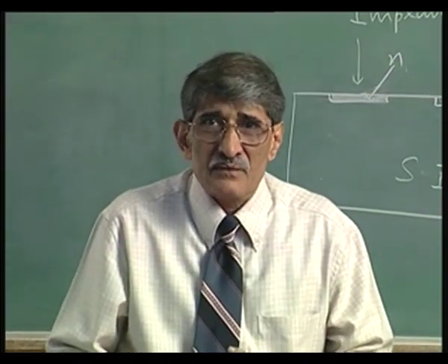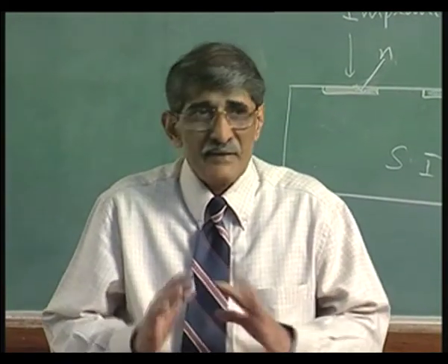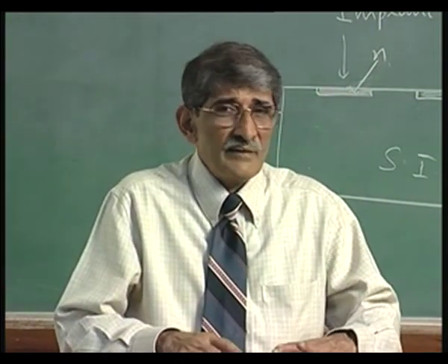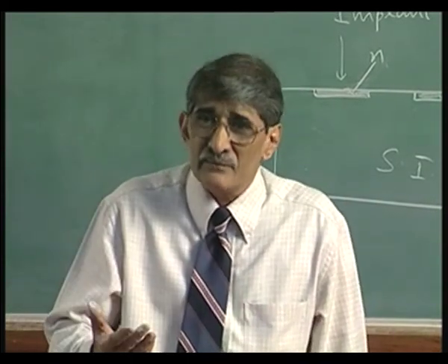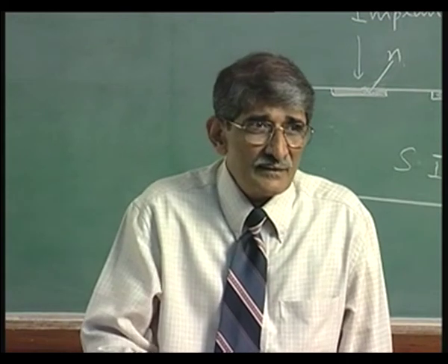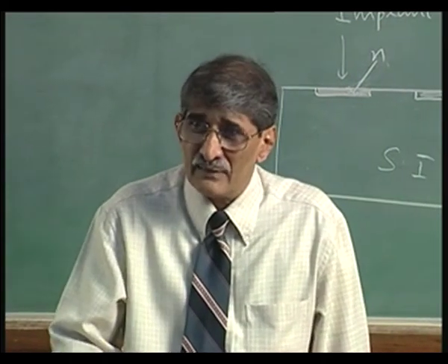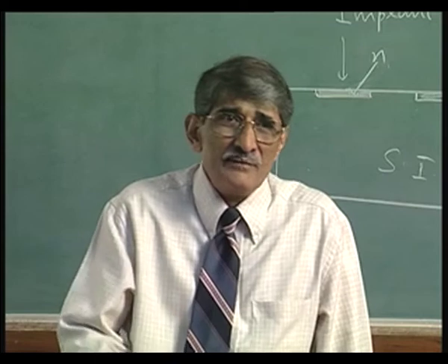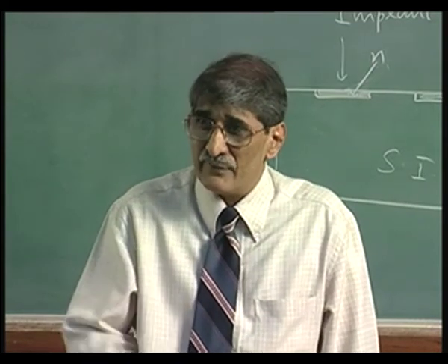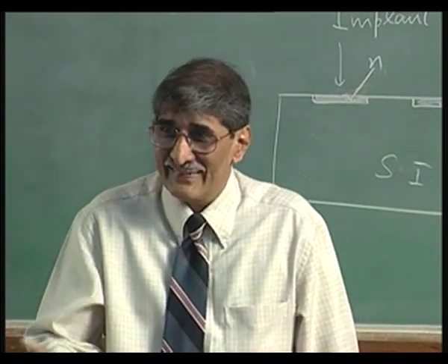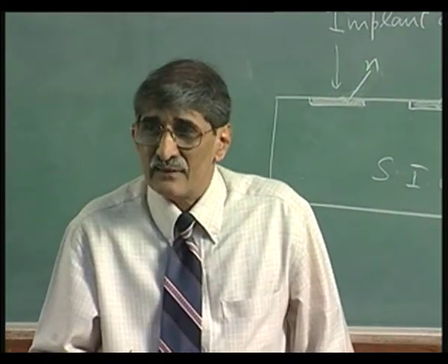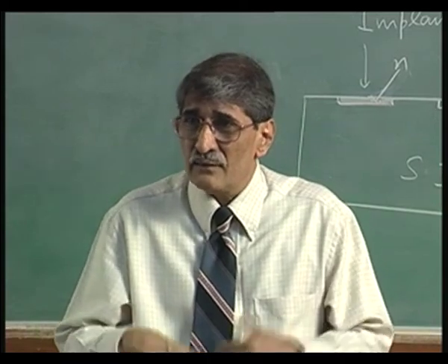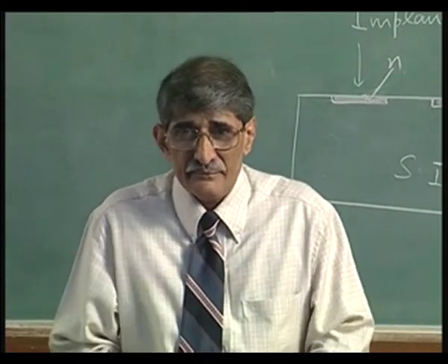We are ready now with the material, semi-insulating substrate, epitaxy or implanted, then make device. What sort of devices do we make? Whether it is a MOSFET, is it feasible to make a MOSFET? That aspect we will discuss first. If it is possible, you do that. Otherwise, go to MISFET, not MISFIT, MISFET. Okay? That is MIS, instead of using the native oxide, some other insulator. That sort of thing we will discuss in our next discussion.